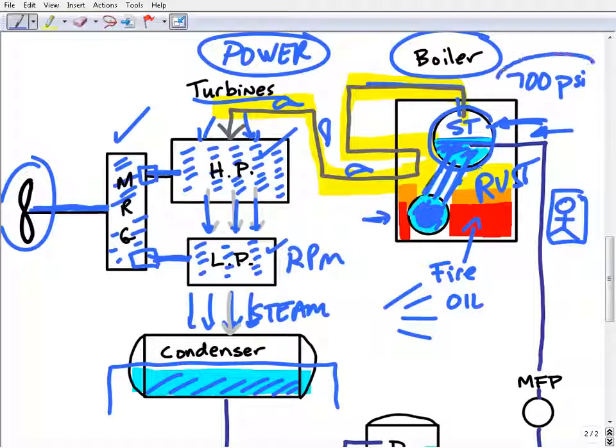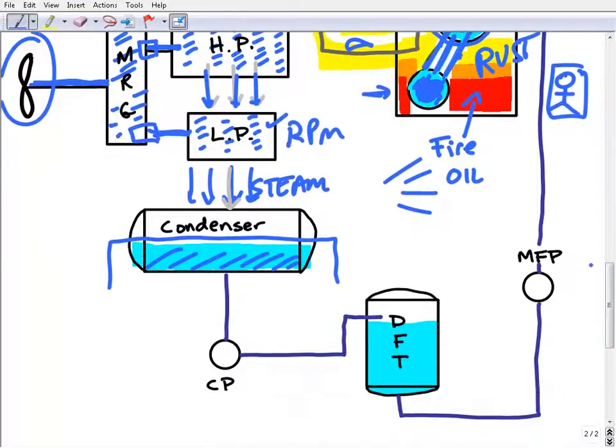And believe me, the last place you want to have any little pinholes or rusting or weaknesses is around something with 700 psi of steam. So very, very dangerous. We have to be extremely cautious about having water that's treated to reduce rusting. Once again, this is an oversimplification, but I think it captures the gist from an engineering standpoint. So that's why we want to recapture this water. Remember, we're using chemicals, it's treated, so we don't want to just continue that on. That would be very expensive and really inefficient. So that's why we have the steam cycle.